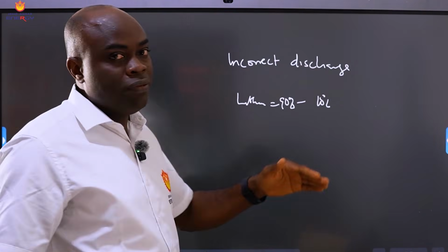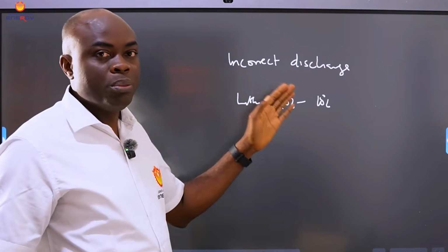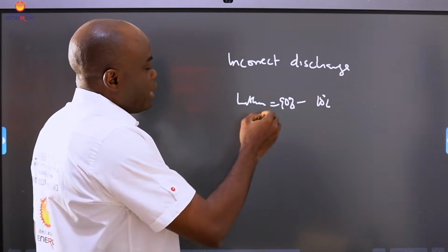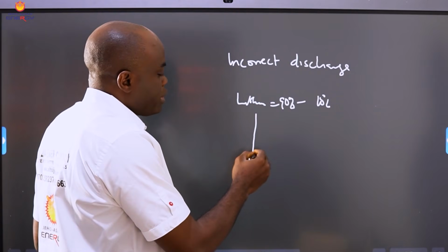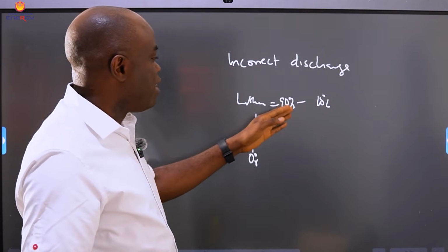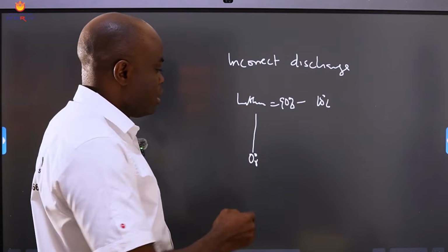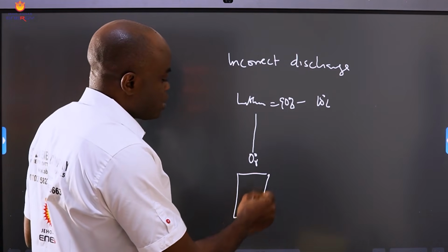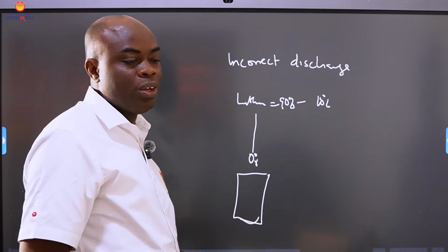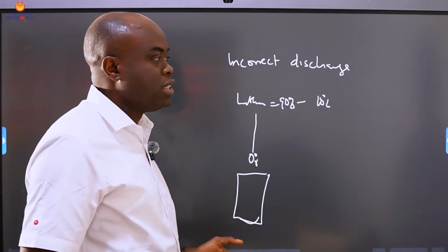For your inverter, if you did a custom setting without any communication between the BMS of the battery and the inverter, that inverter will discharge your battery to 0%. Yes, it will do that. That's why most of the time you get to your site and you see that your battery is dead, like there's no charge inside of it, as a result of there being no communication with the inverter. When your load is connected, the load keeps discharging the battery, keeps discharging it.